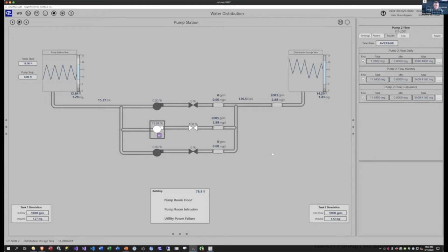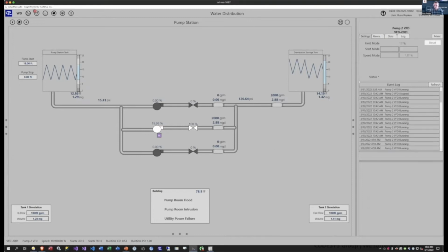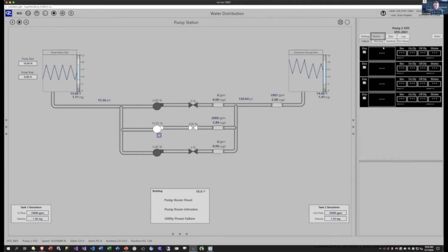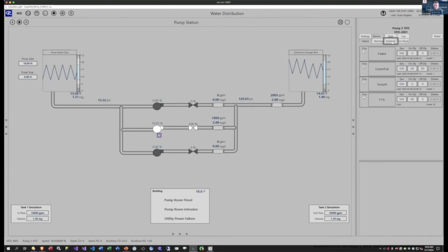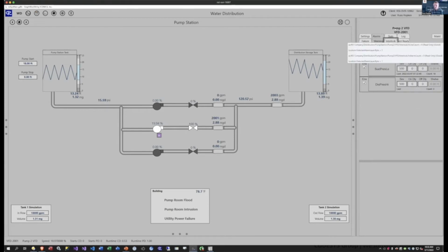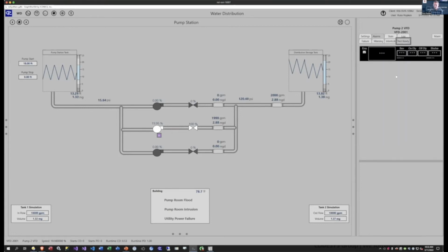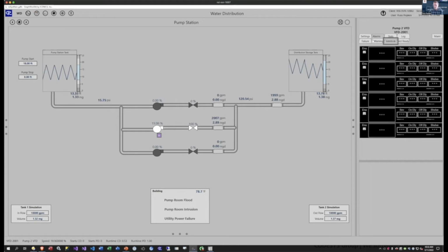Now, equipment are a little more involved, but there's still some commonality. We have those 4 alarm groups. So if I go to the alarms tab on my pump here, you'll see that I have my 4 groups: failure, warning, interlock, and not ready. And in this case, I'm only using 4 of the failures. Things are getting slow this morning. 3 warnings. I don't remember how many interlocks. And then my not readies. So this is all common items for my equipment object.